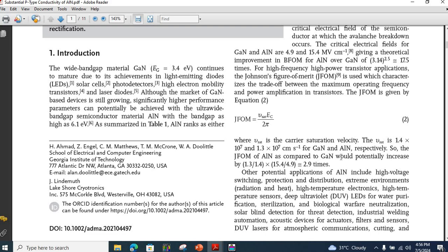The reverse breakdown characteristics of high power devices play a crucial role in ensuring their reliable operation, protecting them against over voltage conditions, minimizing power losses, and enabling efficient performance in various high power applications. High power devices often operate in applications where they need to withstand high voltages without breakdown. Reverse breakdown voltage is the voltage at which